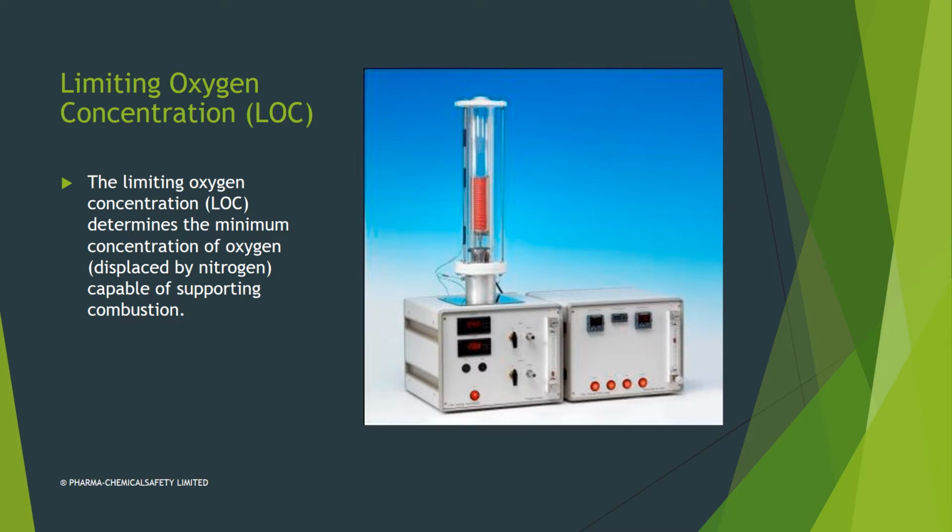Another parameter that is critical is the limiting oxygen concentration, known as LOC, and that's going to help you with, if I recall, NFPA 69. What's this value? It's the minimum concentration of oxygen capable of supporting combustion. So I'm gonna give you an example.